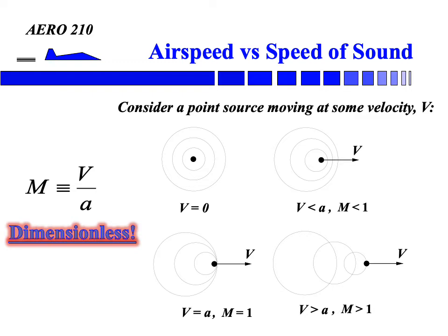They allow us to compare two different situations that have matching values of a dimensionless parameter. So for instance, we might have a wind tunnel test of a model of a full-scale airplane, and then we might also have the actual flight test of that full-scale airplane.